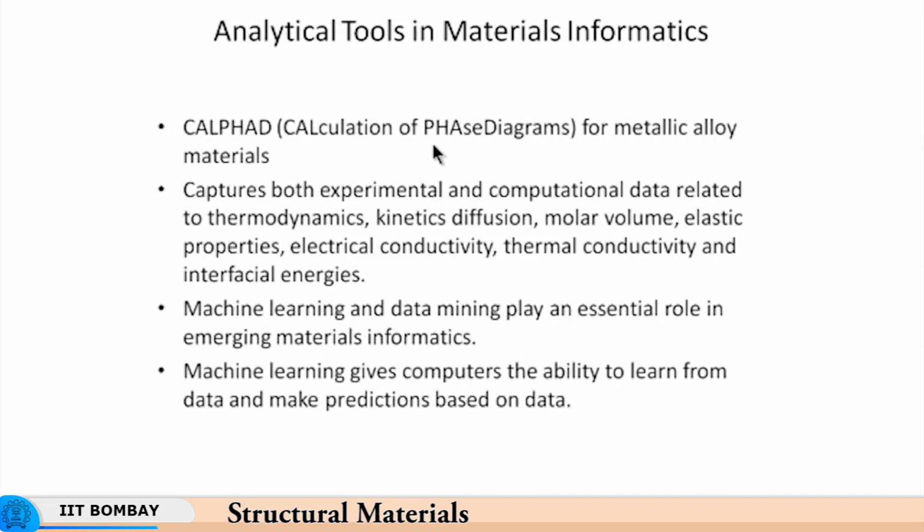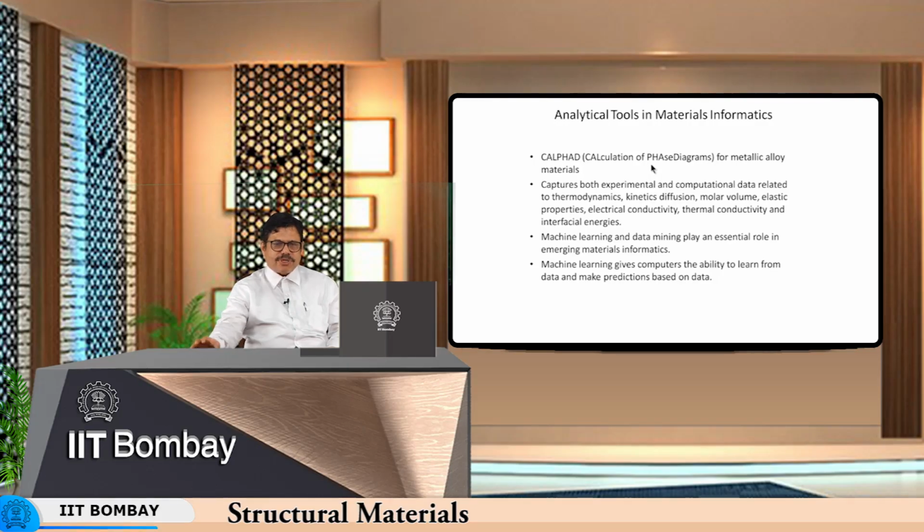Now, we have some analytical tools in materials informatics. So, I will just briefly go over one major tool, which is CALPHAD, which is calculation of phase diagrams, which are so fundamental to our understanding of phase transformations as well as heat treatments. So, it captures both experimental and computational data related to thermodynamics, kinetics of diffusion, molar volume, elastic properties, electrical conductivity and so on.